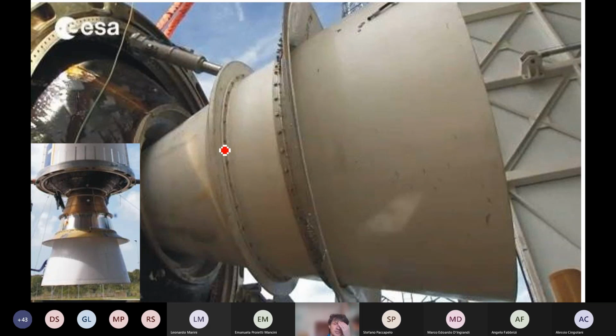Yes. So this is the Z23 nozzle. It's a solid rocket, and you see this is not optimized to have the higher thrust coefficient, even if it's an upper stage. There is a problem in solid rockets, which will be mentioned later: the presence of solid particles that can impinge along the walls.